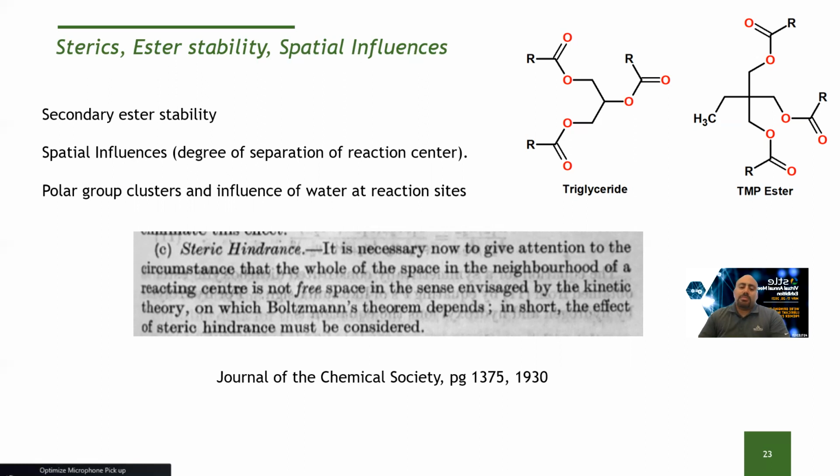And that leads to poor hydrolytic stability. So with Estolides, the spatial influence is that we need separation of polar groups, and Estolides do that. All the polar heads are separated much more than in some of these triglycerides or TMP esters shown here.